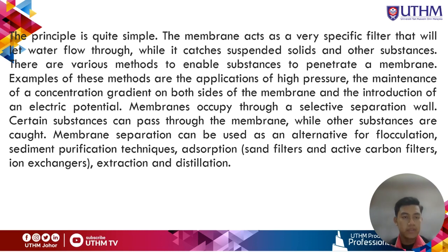The membrane principle is quite simple. The membrane acts as a very specific filter that will let water flow through, while it catches suspended solids and other substances. There are various methods to enable substances to penetrate the membrane. Examples of these methods are the application of high pressure, the maintenance of a concentration gradient on both sides of the membrane, and the introduction of an electric potential.